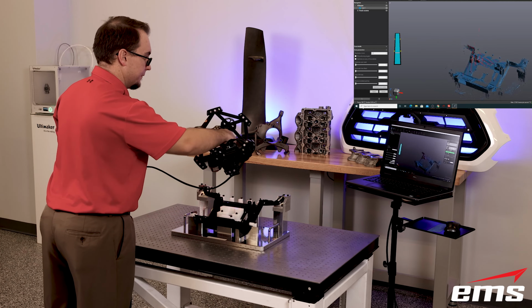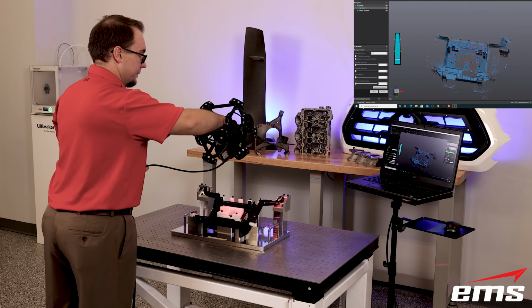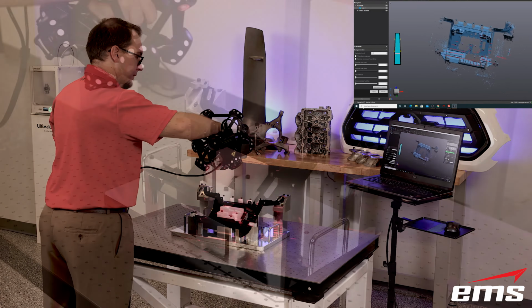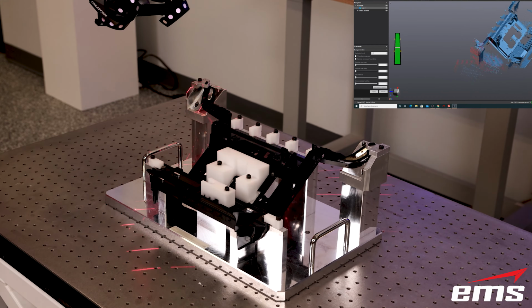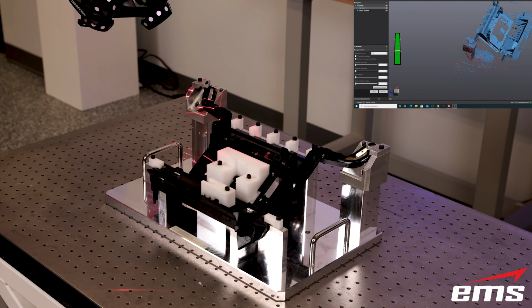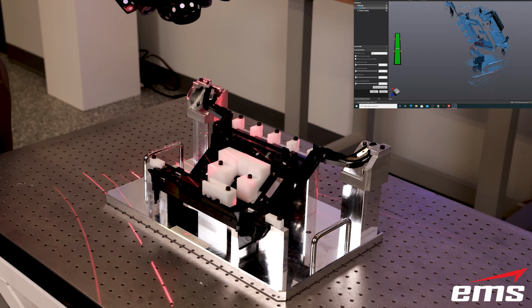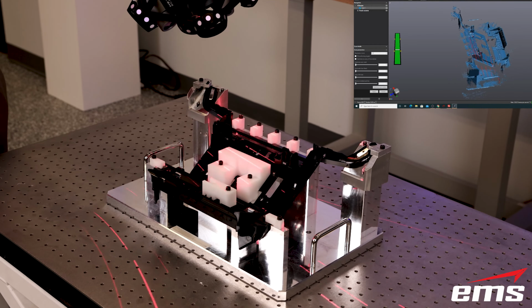But again, this is a case where you absolutely have to have a fixture because of the distortion of the part coming out of the mold. And this is not uncommon in thin-walled, injection molded, and sheet metal type parts, just because of the way the manufacturing process works. In plastic parts, it shrinks. In metal parts, you can get springback. You can get different things. And so that's why you absolutely have to fixture those parts so you know that they are correct.